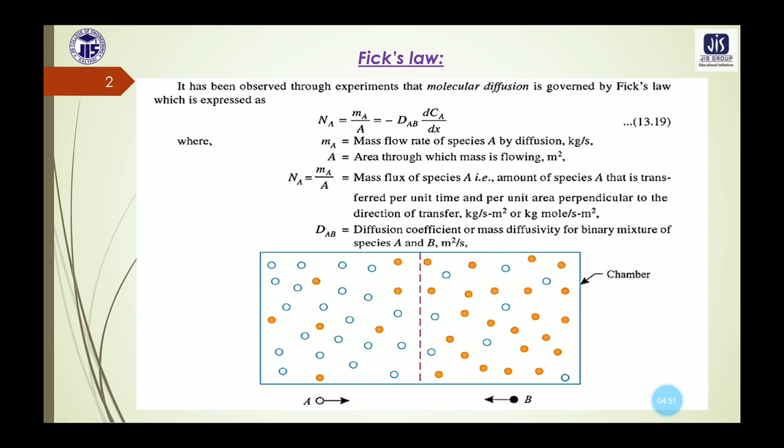From this concept of the eddy we can get the idea that in case of eddy diffusion, the diffusion's nature will be turbulent. That means when one of the diffusing fluids is in turbulent motion, then eddy diffusion takes place. Now, in case of this eddy diffusion, the mass transfer is much more rapid compared to the molecular diffusion.